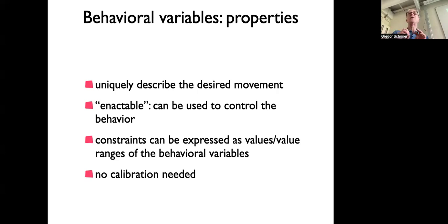I translate the plan of heading direction into a plan of wheel speeds, but I still have to make sure that the physical wheel speed actually is the speed that I wanted to impose. And servo control means I'm measuring really the same variable. I can estimate directly the wheel speed. Servo motors have a little encoder that determines how quickly the shaft is rotating.